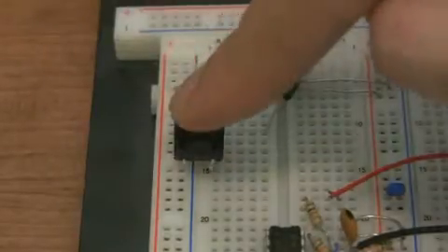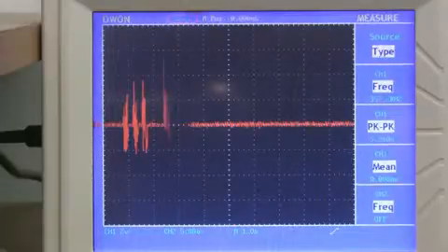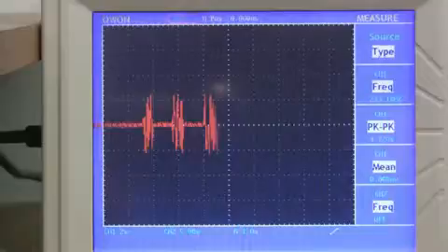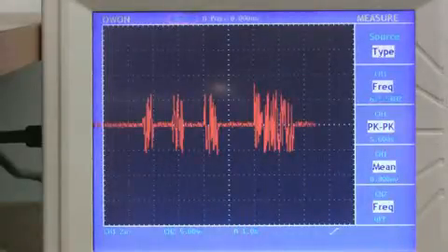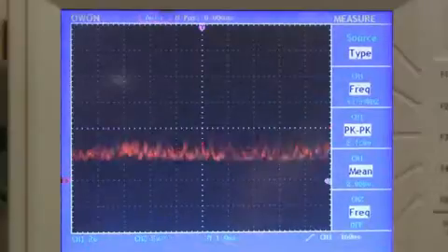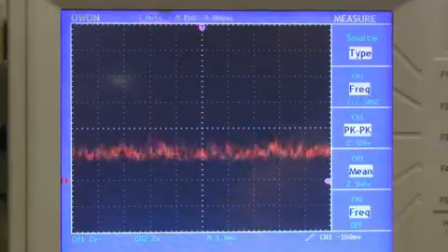But when I started turning the oscillator on and off by hand, I was able to send out messages in Morse code. The process of manipulating the carrier wave to carry useful data is called modulation. And there are many ways you can manipulate a carrier wave, but one of the easiest to understand is amplitude modulation. AM allows you to send an analog signal, like your voice, over long distances.